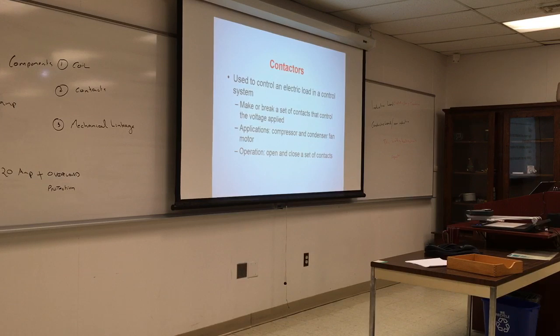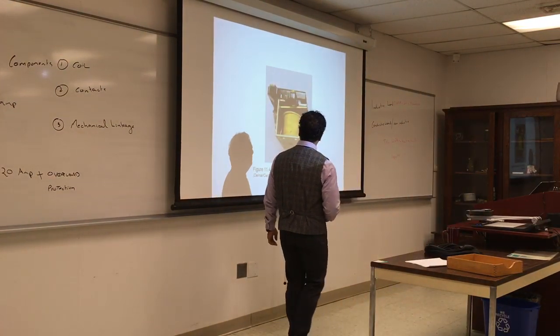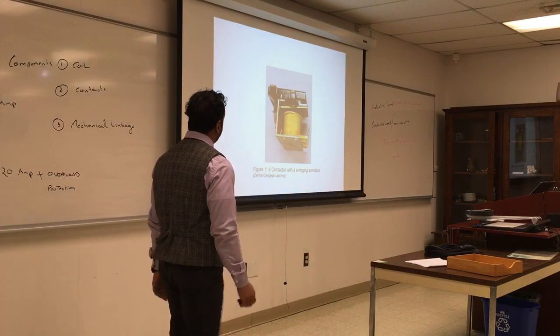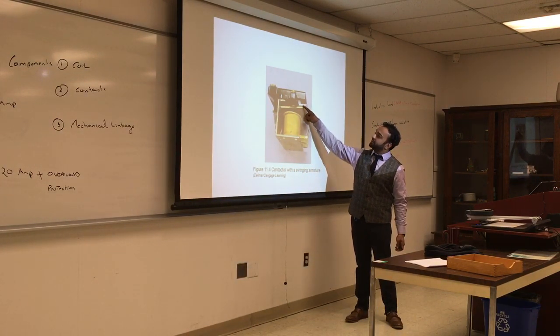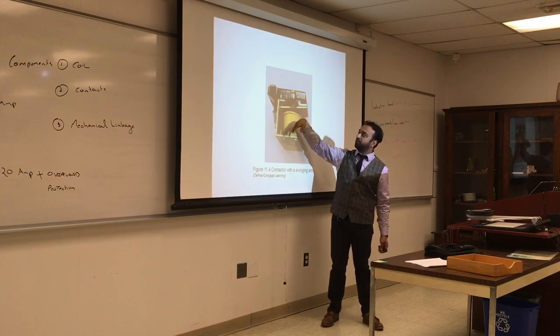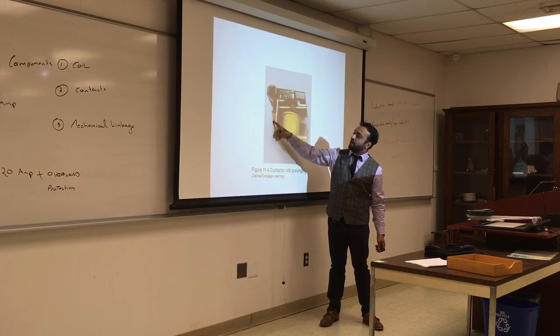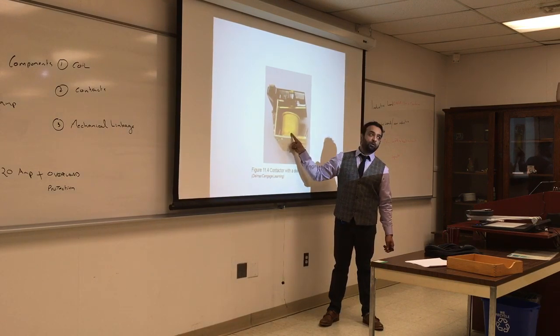Probably if you go into your laundry room, where you have your washer and dryer, you can see this big switch over the dryer, over the water heater. This is a contactor with a swinging armature. So again, if we were to identify the components, this is my coil. It's wrapped up here to protect it. This is my mechanical contact, and you see this thing will be swinging back and forth. So it's going to be my mechanical linkage, armature, and these are the contacts here. And this spring will just give it some power, so it will be moving freely, because the contactor here will work only in one direction.